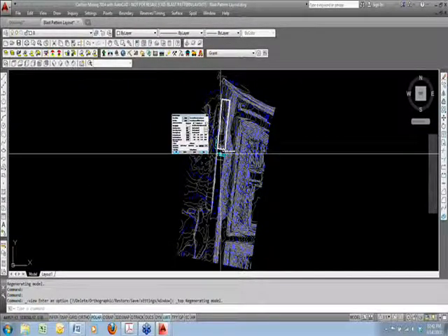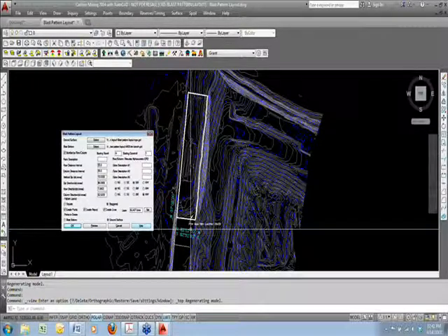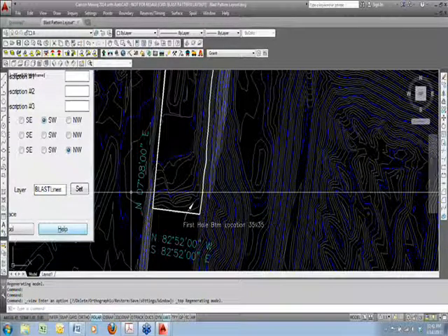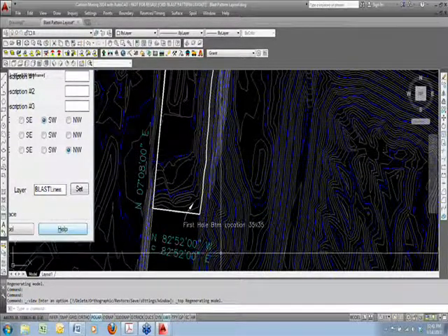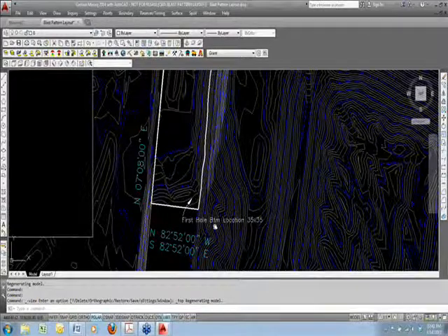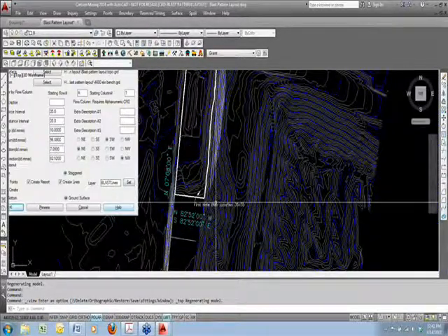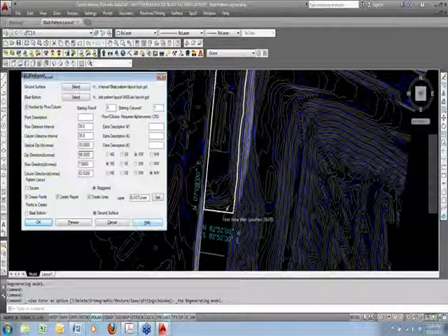All right, so I've got a perimeter. You first draw an outline, and then you also need to know the bearing. So my rows are going to go north 7 degrees east. My columns are going to go north 82 degrees west. And the same as the dip. I want the dip of my holes to go at that, we'll go 10-degree holes.